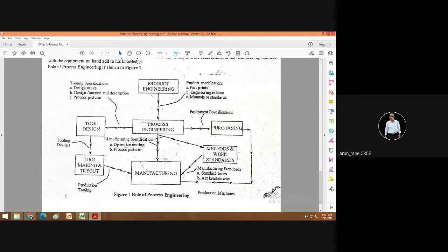and there are certain allowances which are kept in an injection mold or blow mold, which you come to know only after taking the trials, how and where the shrinkages are happening, how the dimensions are getting reduced. Then accordingly they make changes in the tool or the mold, and then a second trial or maybe the final trial is taken. Normally, remember, in two trials your die, your tool should be okay. The moment the number of trials exceeds, you go into loss.